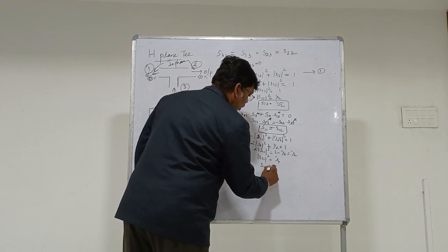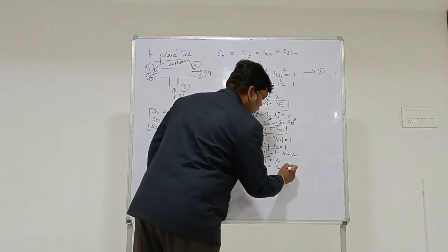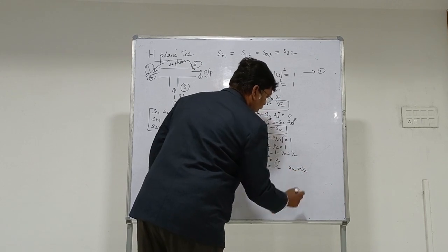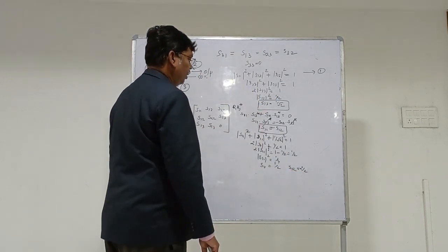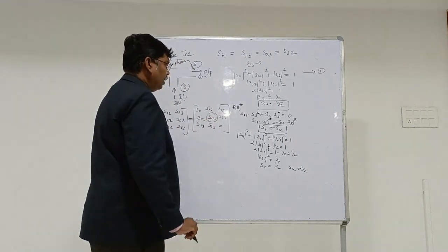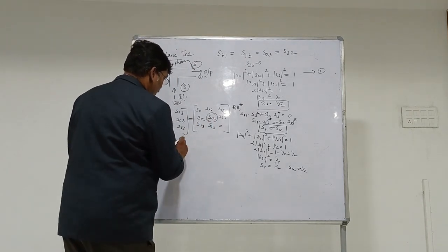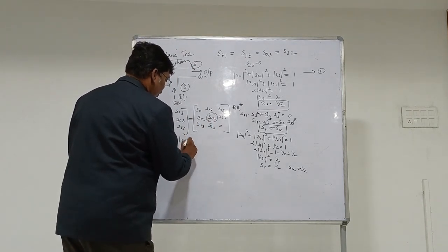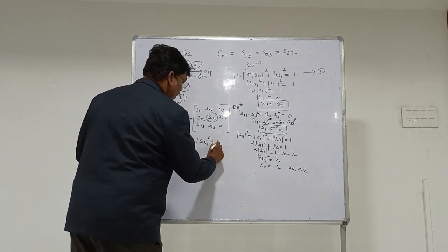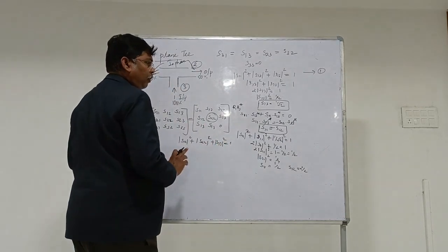Now your S11 is equal to 1 by 2. With S11 as 1 by 2, S12 is equal to minus 1 by 2 with respect to S11. Okay. Then we are supposed to find out the value of S22. For this, I am writing the equation for row 2 with the row 2 complex conjugate. That means modulus S12 squared plus modulus S22 squared plus modulus S23 squared is equal to 1. This refers to the unitary property.